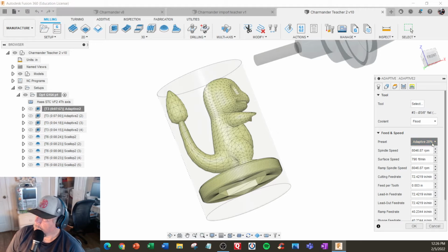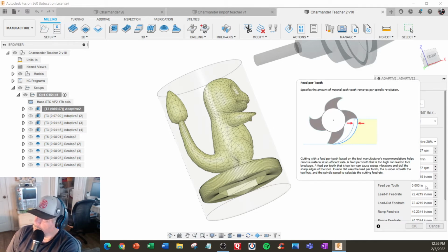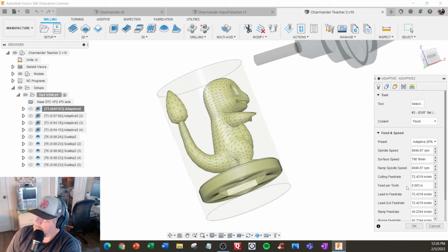Over here, even if I forget to select up front, I have my selections here, and I can pick one. This is going to be 4-axis, so normally we're doing 30% for a regular vise job mill, and we decided to be a little bit lighter, 20%. Our other machine can run 8,000 RPM, so we have an advanced library and can take advantage of that one. We have 3,000 per tooth, so we're a little lighter on the feed rate and less on the step over. These are all pre-settings in here.